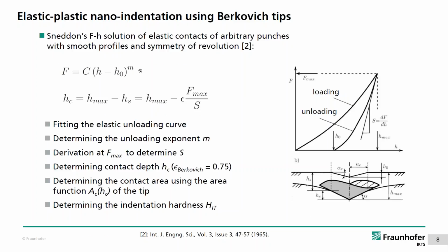So what is the principle of the analysis of these nano-indentation data? In principle you use Sneddon's solution for force displacement curves, and this comes out to a formula like this. And using this formula, here you have the force displacement curve again, you fit the unloading curve because you assume the unloading is fully elastic.